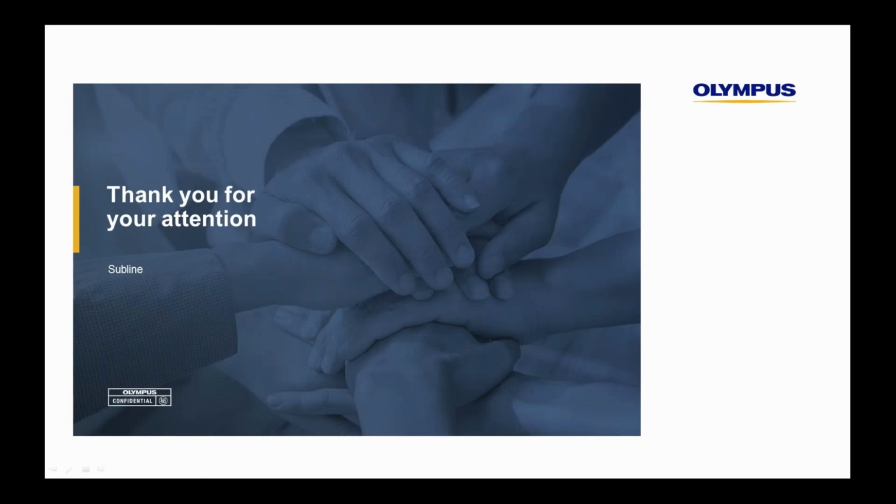But generally, there would be a condition monitoring system in place, and then remote visual inspection would be used at a point of entry to go and check to see if there really is a problem, if you're getting a false reading as an example, or to determine what that problem is before stripping down the machinery.